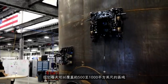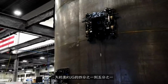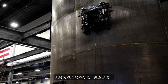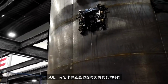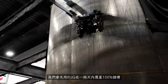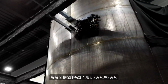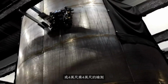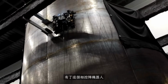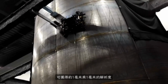It can do about 500 to 1,000 square feet a day. So roughly 1/4 or 1/5 of the typical what RUG could do. So it takes much longer to do a whole tank with it, which is why you want to use RUG on the whole tank and in just 1 or 2 days cover 100% of it, and then come in and maybe do a 2 foot by 2 foot, a 4 foot by 4 foot, and 5 to 10 areas of interest, maybe near a fill line or some corrosion area with this phased array robot, and you'll get about a 1 millimeter by 1 millimeter resolution.